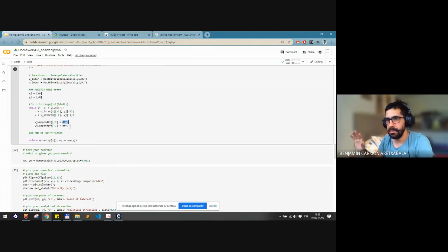Okay, so the main point is to realize, because we didn't talk about this in class, that the streamline under a steady state is the same as a path line. So if you integrate the position of a particle with whatever method you want, then you get good results.